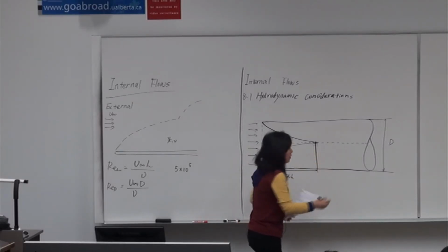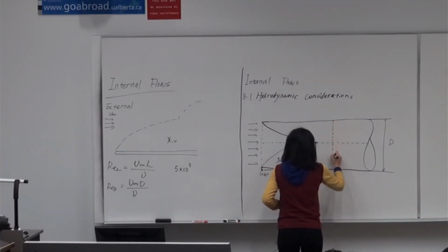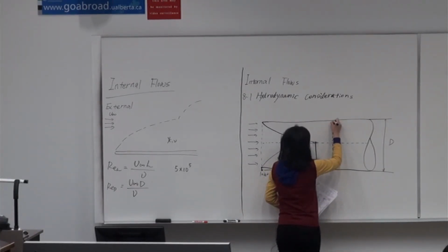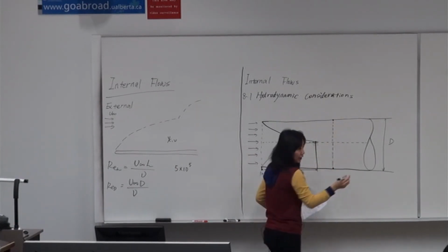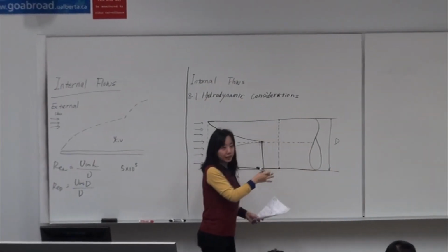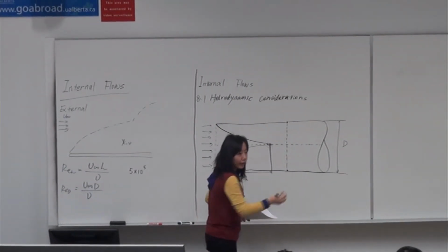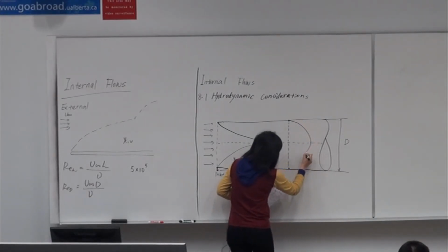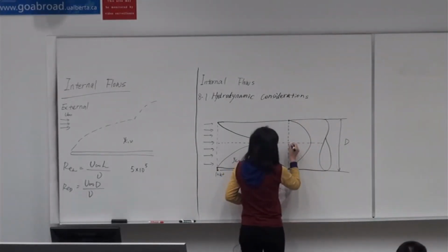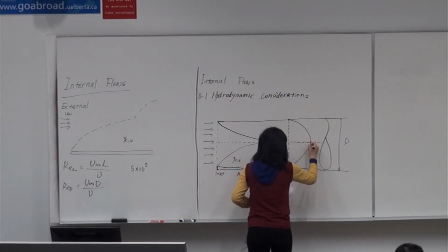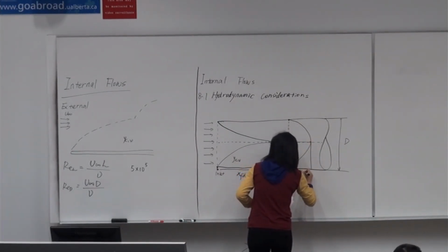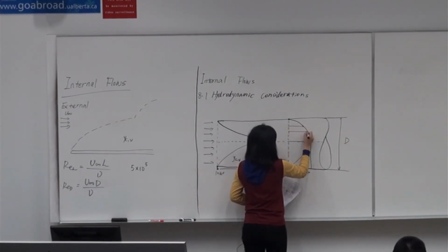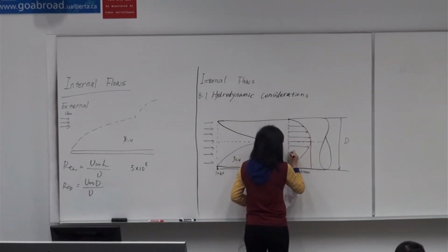after that, the velocity profile is, of course, zero at the surface, and as Wesley just suggested, maximum at the center line. It obeys a parabolic shape. This maximum at the center line we denote as U max, and it is zero on the internal surface of the tube.